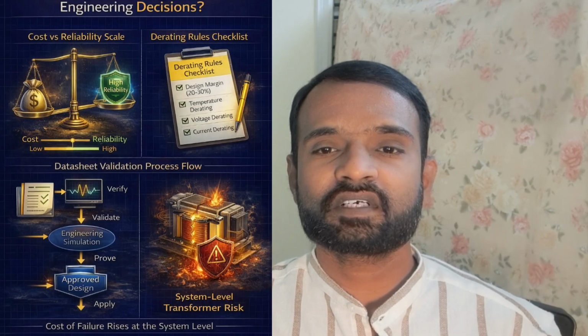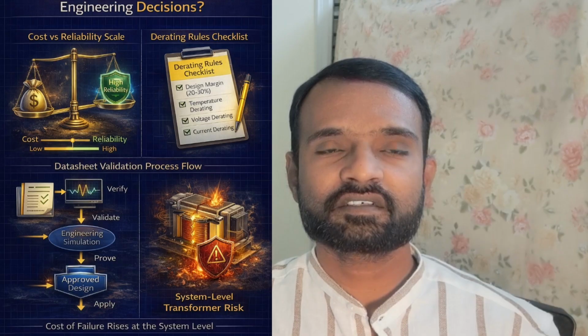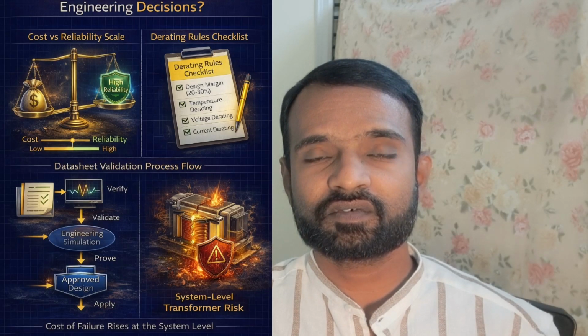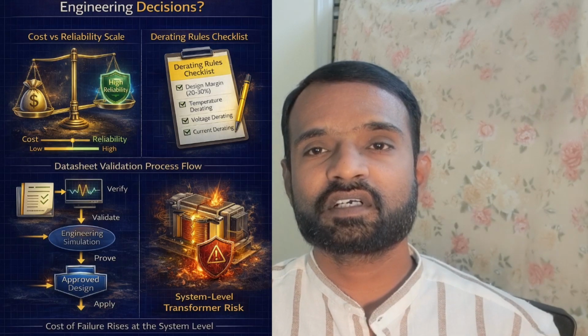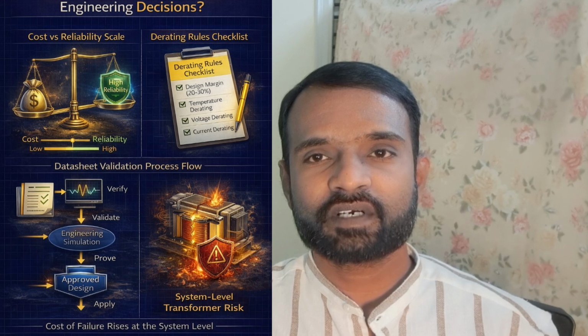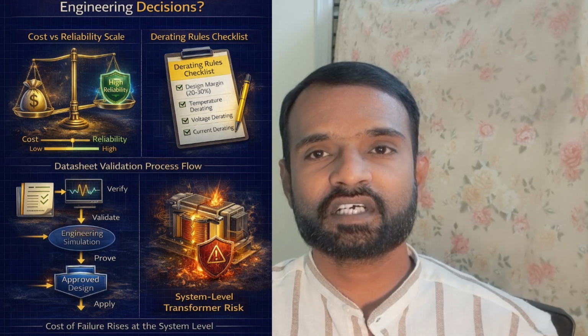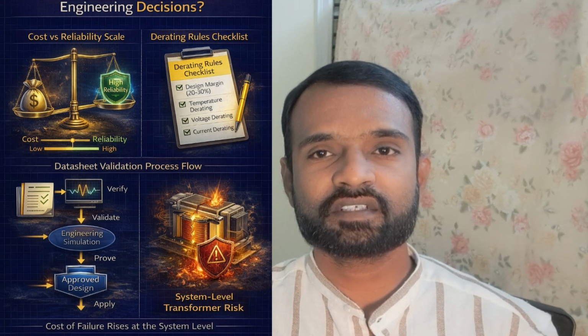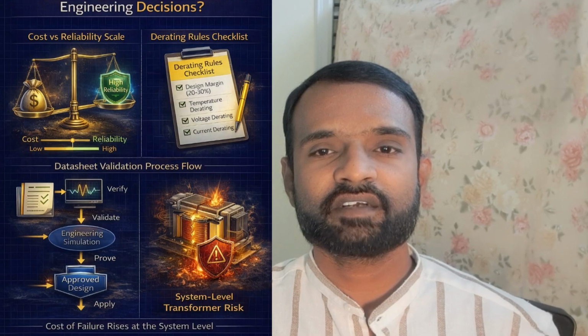Now next comes trade-off. Trade-off is sometimes asked in interview questions where they want to understand that when we are selecting a component, we have to consider the cost as well as reliability. So in this kind of situation, we need to understand that a smaller component size is going to create higher stress, whereas lower ESR comes at higher cost. Example, automotive uses larger and safer components.